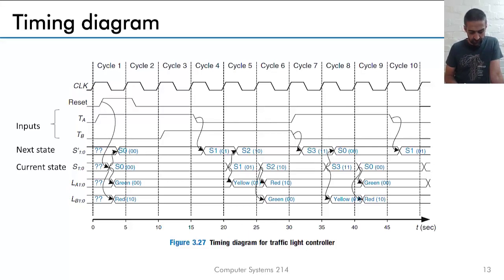So in terms of the first step, we have the reset here. Because we have the reset, we didn't know the values of any of the current state or the output values. So that reset caused the states to turn to 0. So state turned to 0, state turned to 0. That is my next state and my current state. They're all equal to 0. Because the current state is equal to 0, the next state is equal to 0.